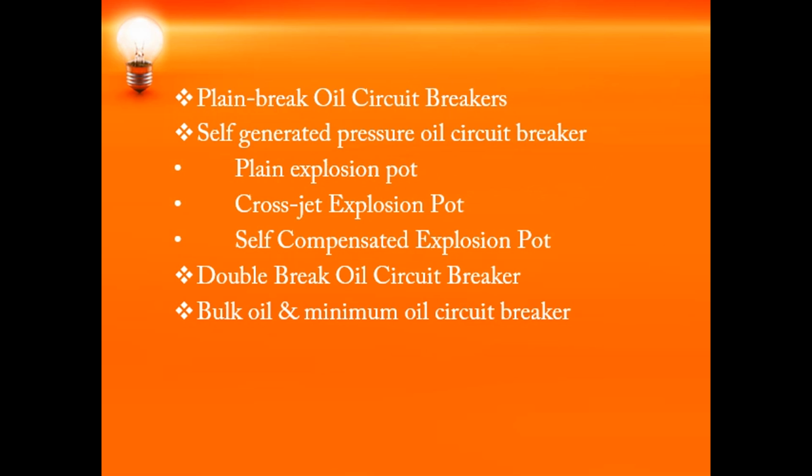In spite of all these disadvantages, a few oil circuit breakers are used for low current interruption, but oil circuit breakers are not suitable for very heavy current interruption, mainly due to carbonization of the oil. So which are the different types of oil circuit breakers available?